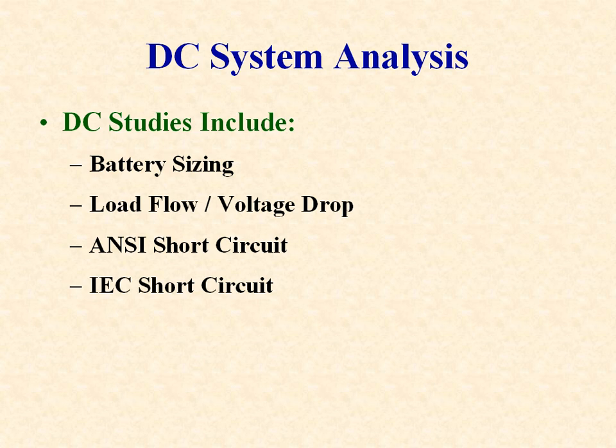The DC System Analysis modules include battery sizing calculations for both lead-acid and nickel-cadmium batteries, time-dependent load flow and voltage drop calculations, and short-circuit calculations using either the ANSI or IEC methodologies.